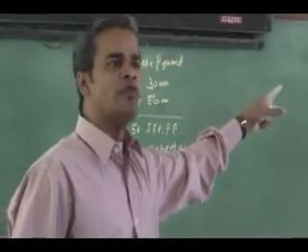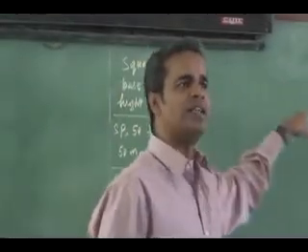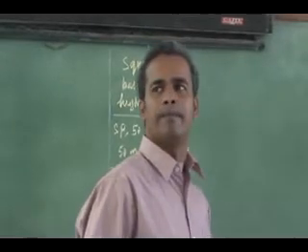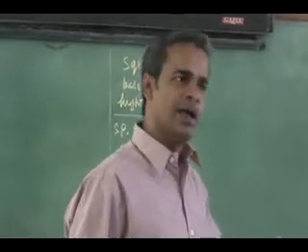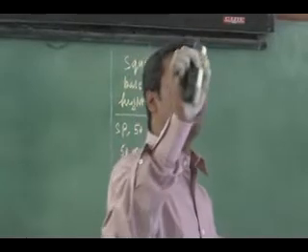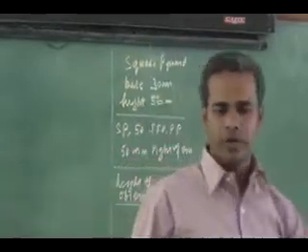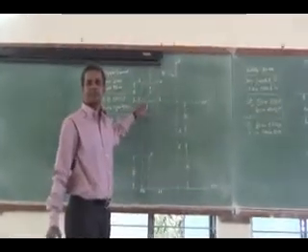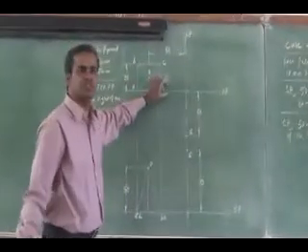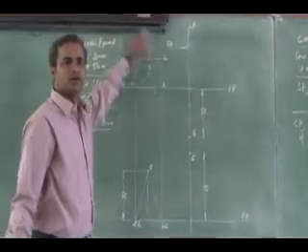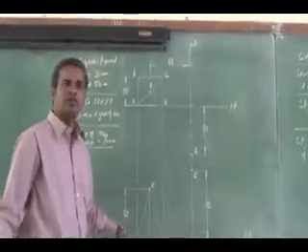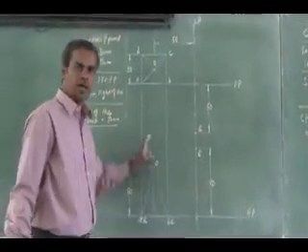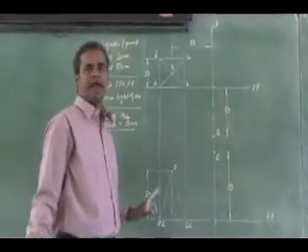The top view will be a square with slant edges. What will be the front view of the pyramid? A triangle. You have to get the perspective location of the apex also. Do it, make it fast. The edge is touching the picture plane, so the top view will be like this, and the behind distance is 0. I have drawn the top view, and I have drawn the front view for the height 50. It will be a triangle.